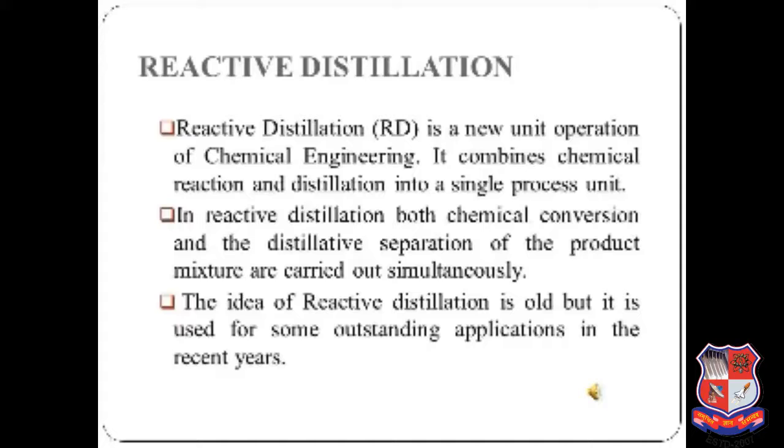So reactive distillation for a particular reaction depends on various factors such as volatility of the reactants and products, along with the feasibility of reaction and distillation temperature. So this technique is very good, but we need some parameters. Based on the parameters, this reaction and separation occurs.